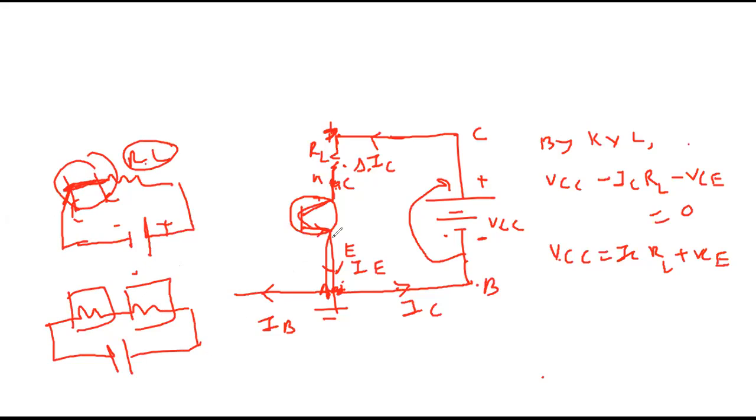So this whole part is our one resistance. The voltage across that is VCE and the voltage across RL is ICRL. So this battery is giving voltage ICRL plus VCE, or not? So can I say battery voltage is ICRL plus VCE, or I use Kirchhoff's law, the meaning is the same. Yes, Patil. Again, the explanation is followed.